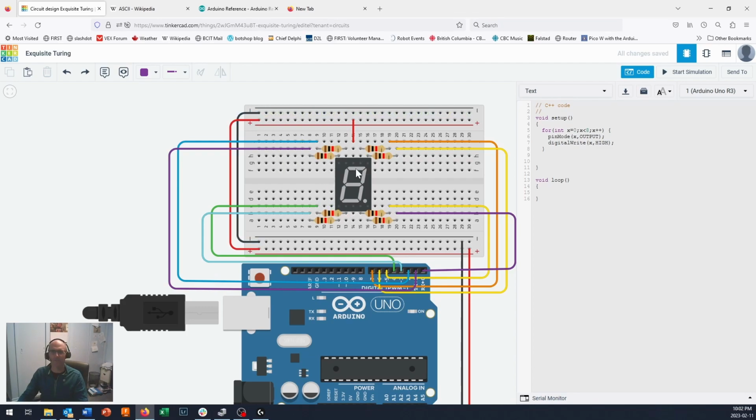So for the number 2, we're going to have A displayed. So we have to come in here and digital write. Okay, then we're going to say 7, comma, low, and that will set on pin A. Then we'll go digital write. B has to be low for this one, so that's 6, comma low. Then we'll go digital write.